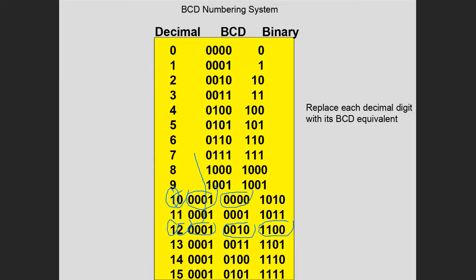That will give you a 0 through 9 for the leftmost digit. And then this set of 4 right here will light up the second 7-segment display. And it too can display the digits 0 through 9. So I can start out counting at 00 and go all the way up to 99. With 2 7-segment displays, I can count up to 99.